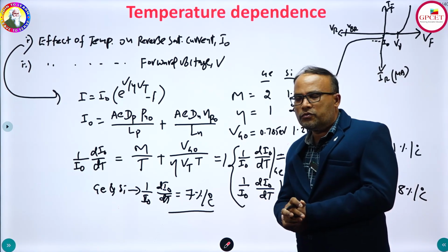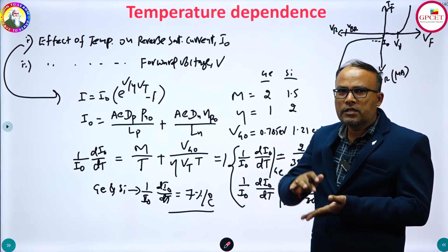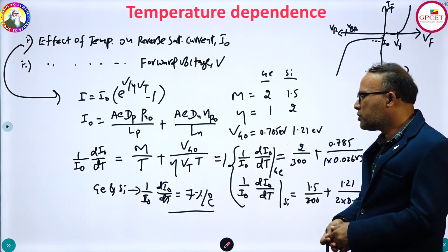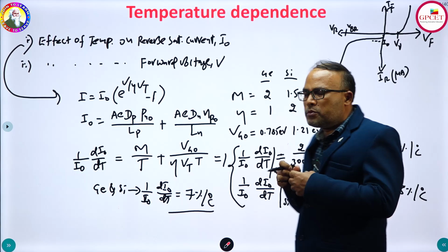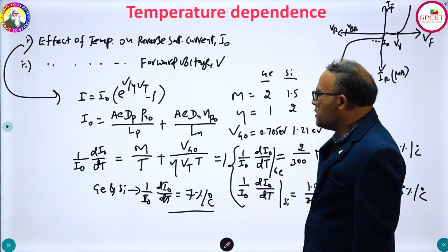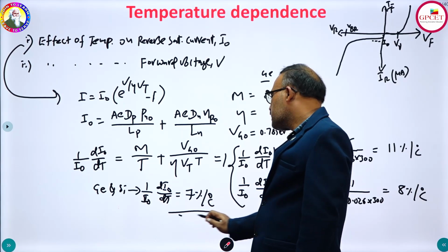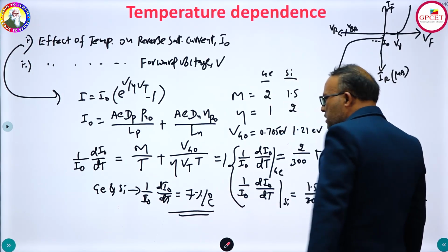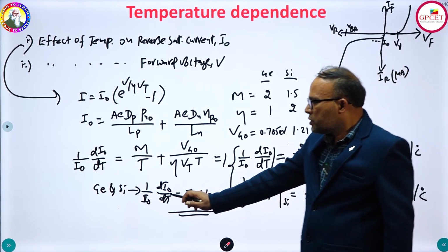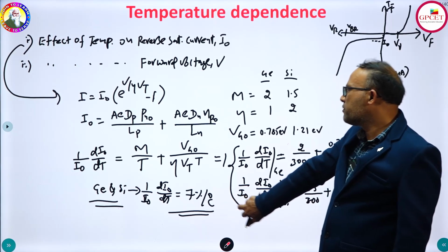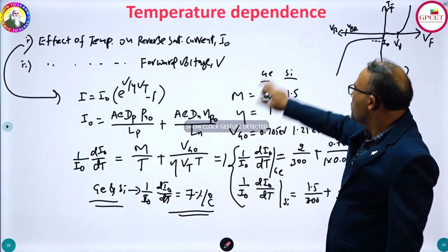are some leakage currents which are observed by the materials which are laid on the surface of the diodes, both germanium and silicon diodes. So some leakage currents will be observed due to those surface impurities. Therefore you get the reverse saturation current as 7% per every degree C rise in temperature. So I can consider the relative temperature coefficient for both germanium and silicon as 7% per every degree C rise in temperature. So if it is 7%, then what happens?